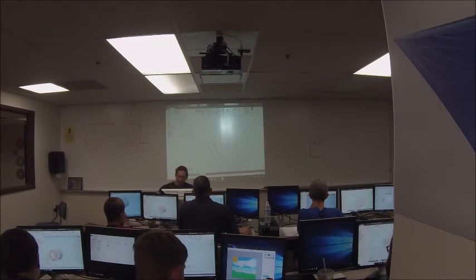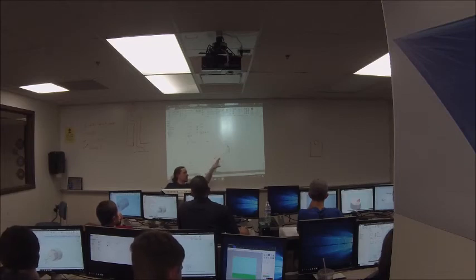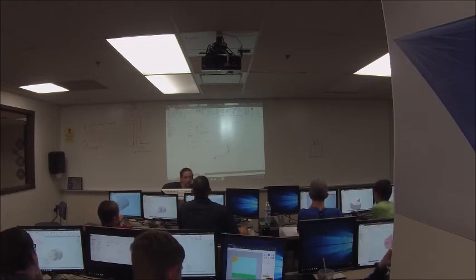Now activate the Extrude Tool, and you'll notice, just like we were talking about before, we have just one profile, which makes one region. So Inventor knows that that's the region that you want to extrude. But we don't want to extrude out. We want to cut in.